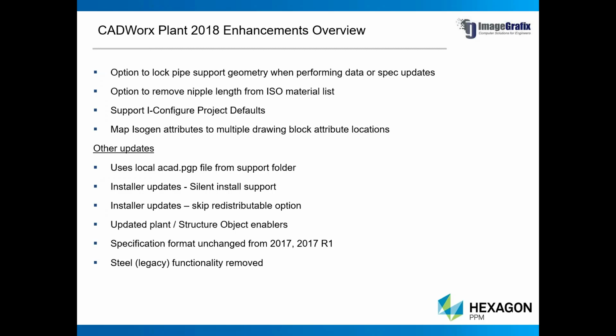Regarding the updates for installation, silent install support is now available. If you want to do a silent installation of your CADWorx, it's possible now. Also, while doing installations, sometimes you find it is not proceeding further, which is basically controlled by the redistributable tools. Now we have options to skip that particular installation. If you have already installed them on your machine, you don't need to reinstall or overwrite those redistributable items.